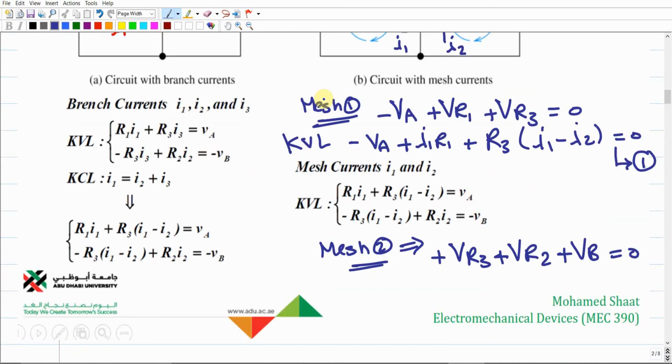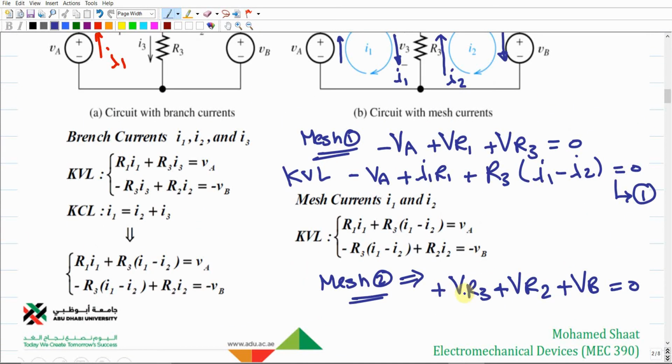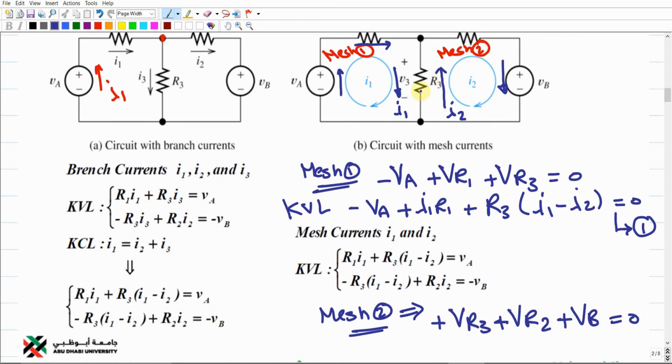Make sense? But anyway, this is Kirchhoff's voltage law, but in terms of the voltage we have to substitute for VR2, so we apply Ohm's law. How much is the current over R3? The current over R3 will be the difference between I1 and I2 as we agreed, because we have two different mesh currents going through the same branch, right? But what is our main reference?